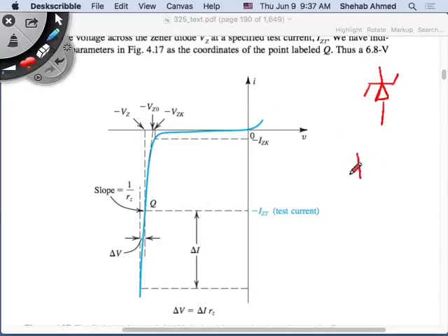So remember the diode model was this, right? The voltage that was opposing the current flow was modeled this way. It was a voltage source, 0.7 volt, that was opposing the current flow. So only when you put a voltage on the anode side higher than 0.7 volts above the cathode side can you forward bias the diode and the current can conduct. So what did I do here? Current is in this direction. No, this is wrong.